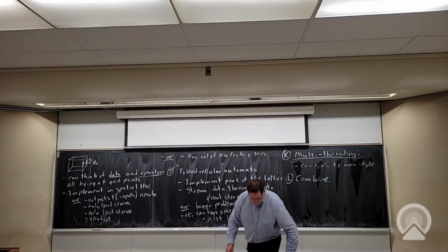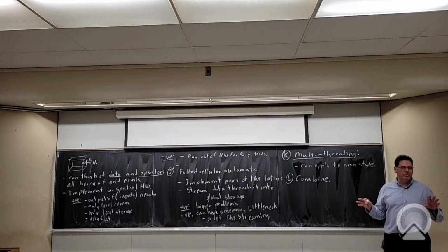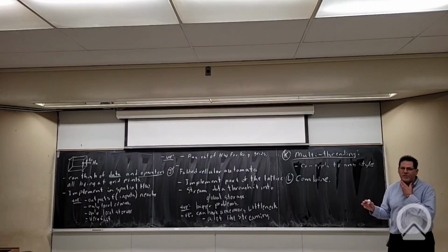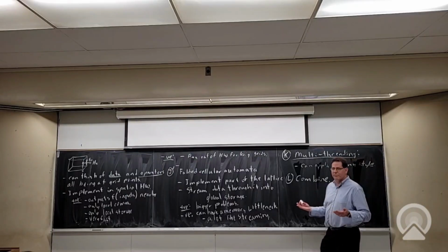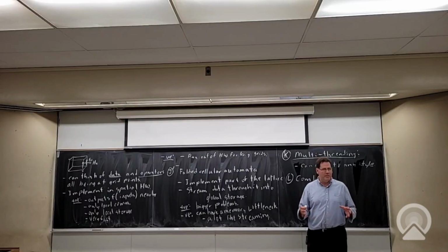And I guess the last thing I'd say, so the simpler models, like we started off with this very simple model of an inelastic pipeline, right? So you can't stop the computation, you can pipeline it with simple registers. So the simplest models tend to be very efficient. If you can map your computation to it, it's a good idea to do so, but they are more limited, so often they can't do everything you need, so then you have to mix in some of these other ones. But I think that's probably a good heuristic.